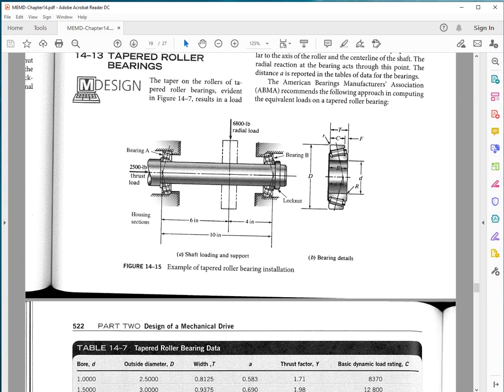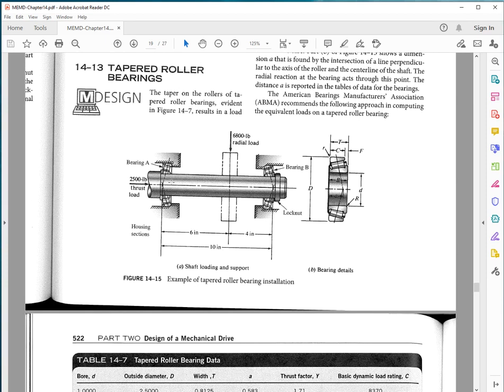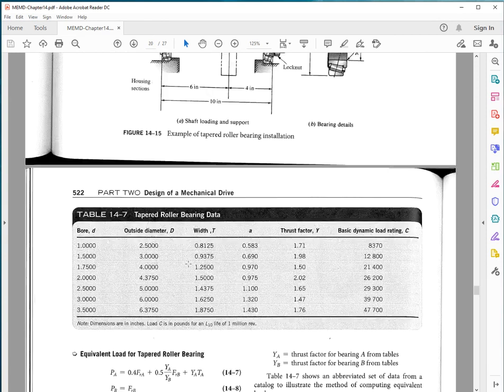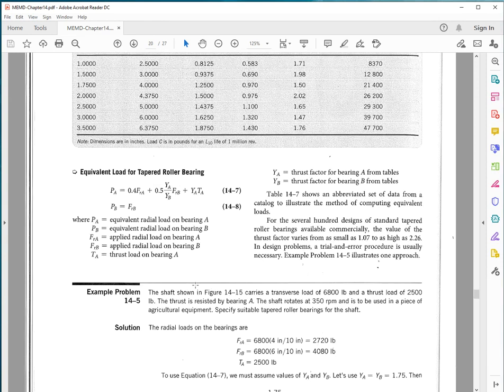See the rear wheels of trucks, or the drum type rear wheels, or in general wheels of automobiles. So you may have one bearing being bigger than the other one, but they are both thrust bearings. And you'd expect the bigger one to be the one that takes the thrust.